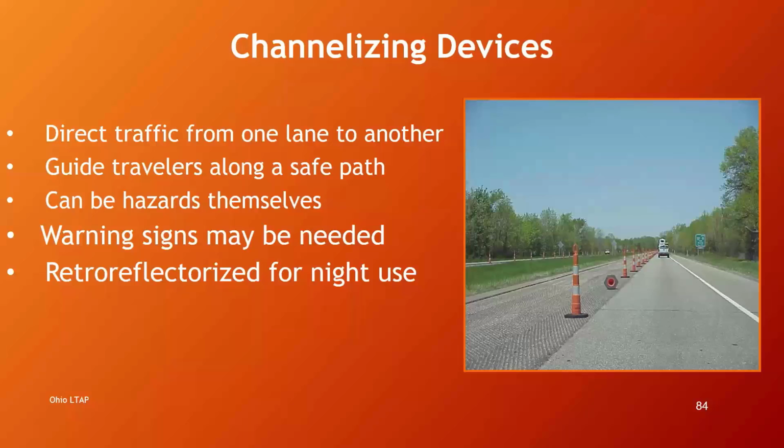One's an illustration and one's the notes page that has the standards, guidance, and options. In the illustration, it'll show you what signs to use, and also show you the channelizing devices placement, with the tapers and how they're installed in the buffer space and the workspace and termination taper.